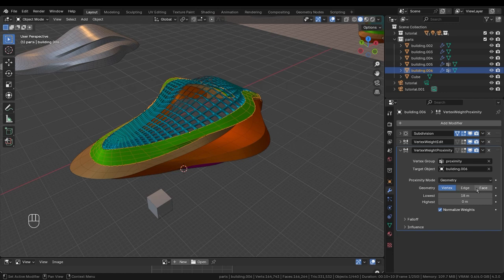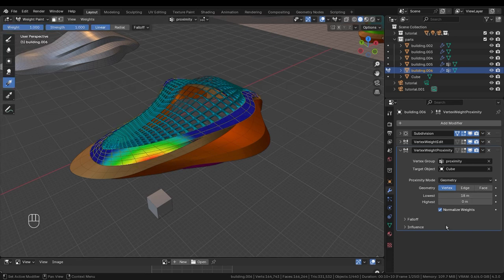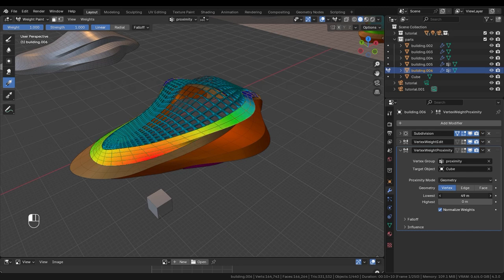I'll click on this panel, I edit this one to be linked to the object, and then if I go to the weight paint, I can adjust the weight paint, and I make the falloff smooth instead of linear. This will give a better transition.